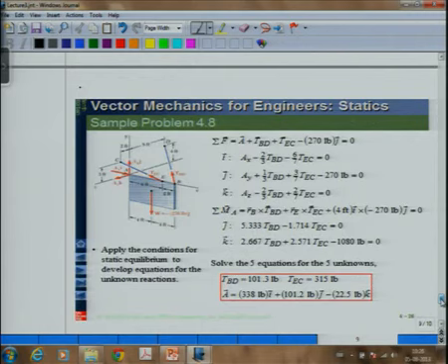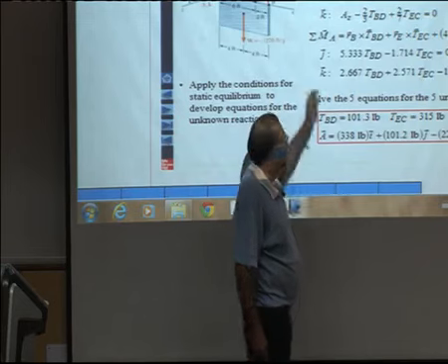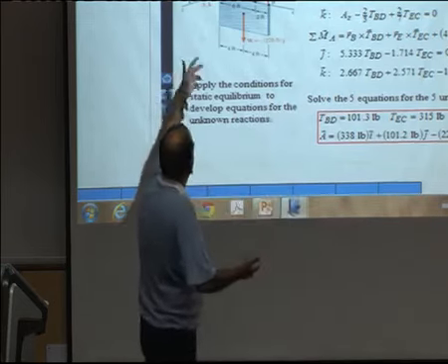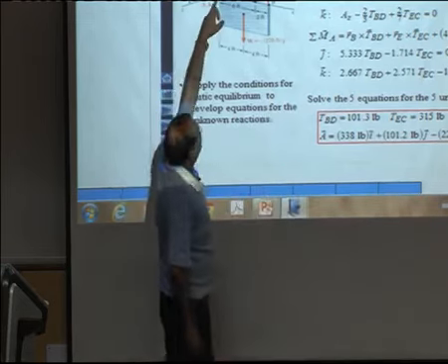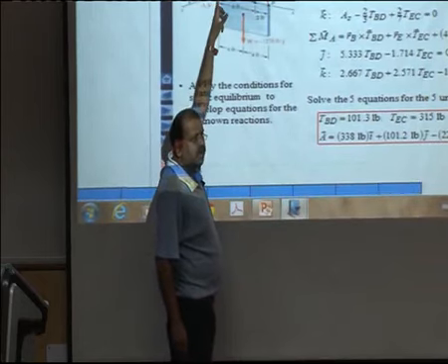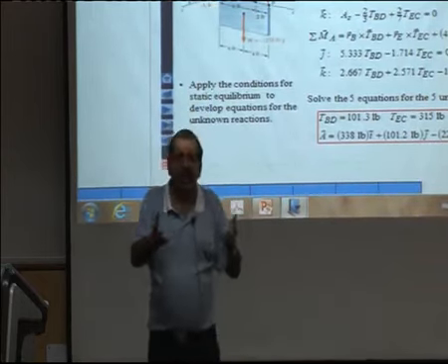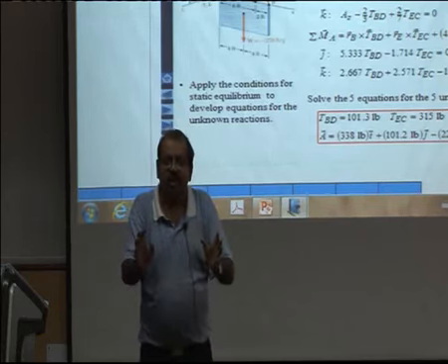And we solve the equations. In this case, the best thing would be for you to just write the vector equations and the scalar components. So, you write sigma Fx is equal to 0. So, you will put Ax, and the x components of the 2 tensions, sum of that is equal to 0, sum of y components, sum of z components, and then you have sum of moments about point A. Again, there are 3 unknowns acting at point A, so choose point A as the point about which you take the moments, and you write just the vector equations.